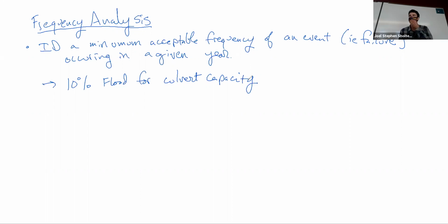Val, what do you think? Just like overflow on the one side that the water's coming from. So we might get some water on the road, right? The road could be flooded. If it's really bad and a culvert is overloaded, so here's our culvert, here's our roadway, and the water is spilling over and coming down, and say this is not armored, you could scour this out and the roadway could wash out, right?